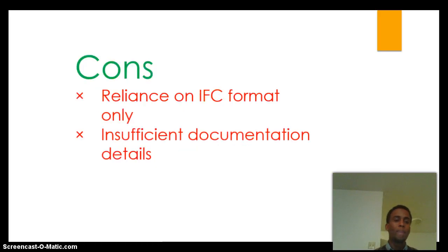One of the main cons or disadvantages of the software is that it's almost reliant on the IFC file format. If you don't save your BIM file in IFC file format, you will not be able to use it on the Solibri model checker. So that's one main setback for the software developers. Its other setback is insufficient documentation details.